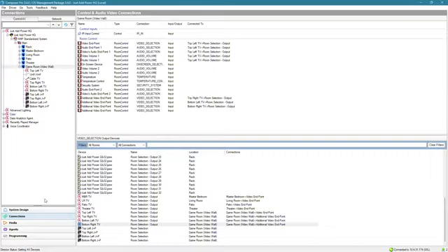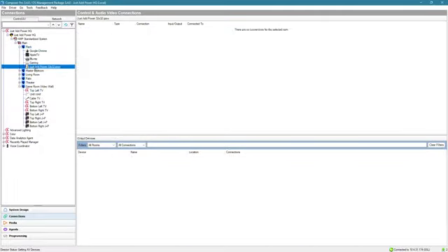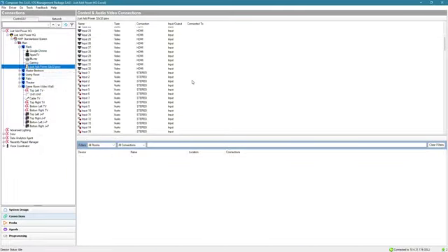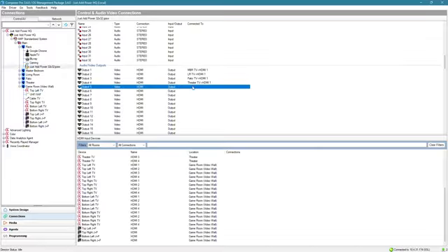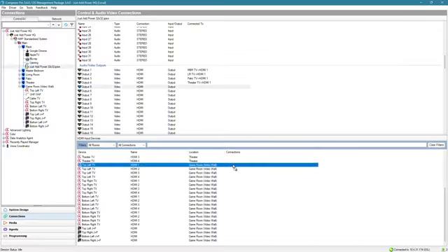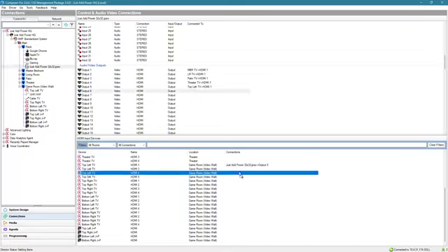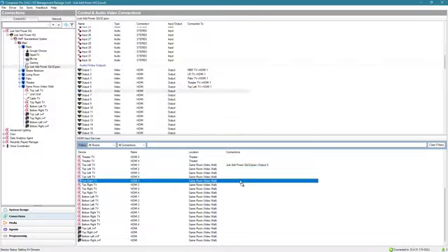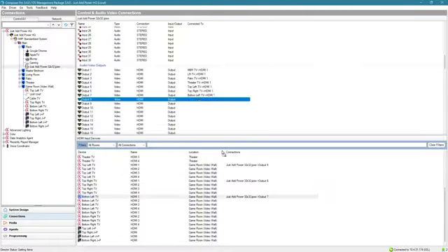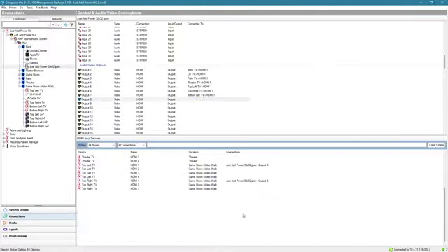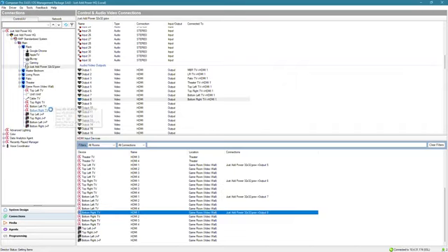The other thing we need to do, because these are new displays in our system, is we need to go to the Just Add Power driver, we need to go down to outputs, and we need to assign the TVs as new outputs for the system. So we've got HDMI 1 connected on all of those. Top right HDMI 1, bottom left, and bottom right. And all of these connections are to the TV drivers themselves.